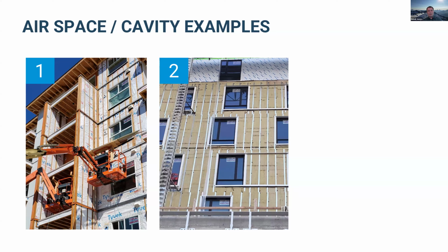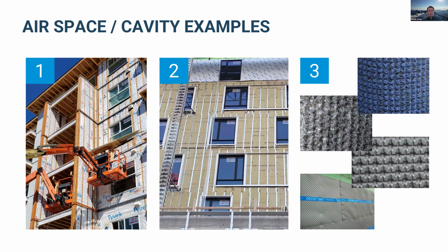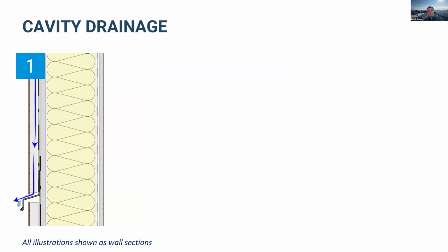Commercial buildings typically see metal studs and more fiberglass or composite materials here. We've got what looks like vertical girts or hat channels in this picture here that are creating that airspace. The cladding is going to go over top of it. We're also seeing quite a bit in the residential world of just dimple mats or drainage mesh products that can create that cavity space, where the siding just gets installed right over the drain mat. So lots of different ways to do it, right?